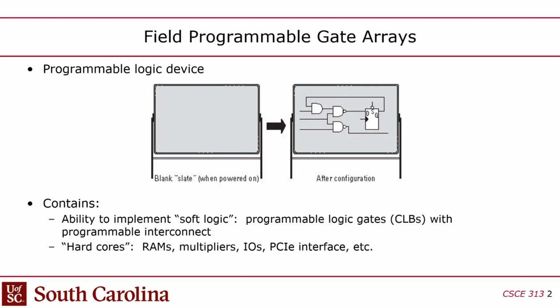And see the state. Like if you're running a CPU in a debugger, on these boards you hit the pause button and it just freezes, and then you can go in and see the state, right? Or you could set a breakpoint. You could say freeze on line 12, and once it hits line 12, it freezes. It hits a breakpoint, and you can inspect the state. You could look at registers, you could look at the memory.